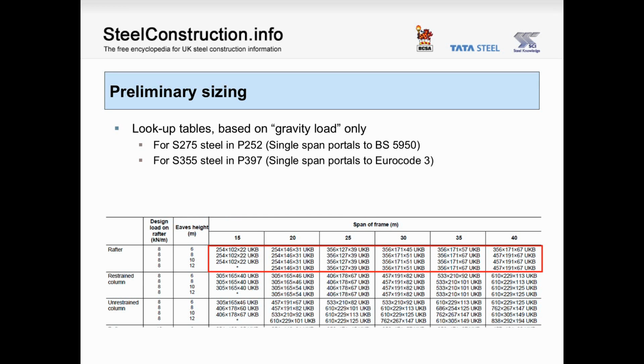If we consider the rafter, then the section size depends primarily on the span, and that's because the bending moment at the eaves concerns WL squared over, let's say, 15, and L, of course, is the span of the rafter.